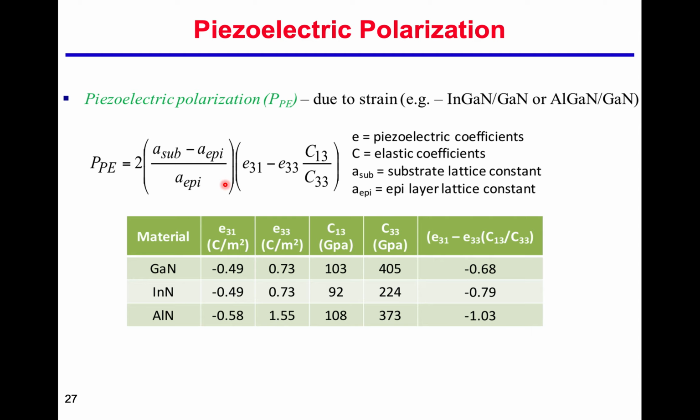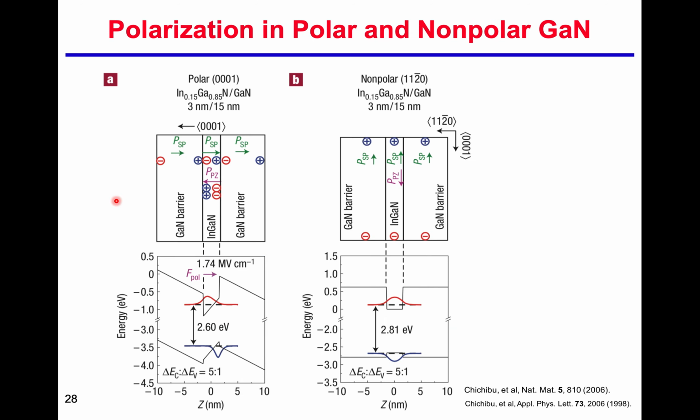Due to the lattice mismatch, which is an issue, there will be piezoelectric polarization. So there is some misalignment because of the polarization here. You can see some dipole here, and it will result in a split in the wave function inside the active region. Sorry, here's the active region, not the quantum well region.